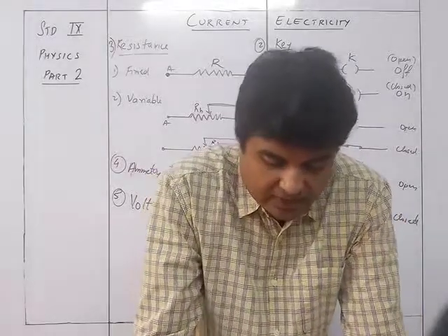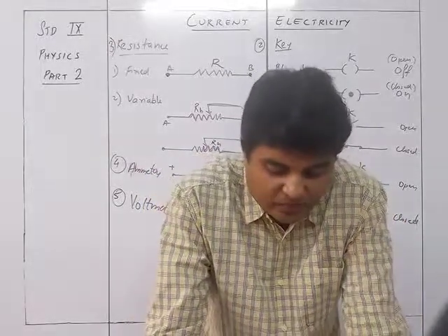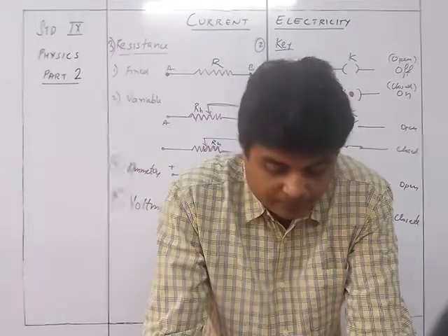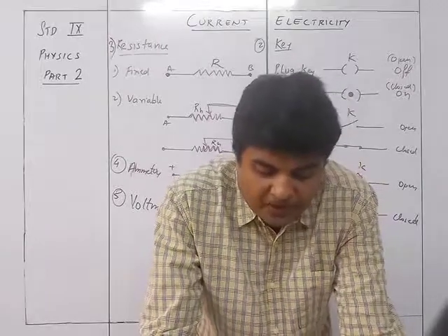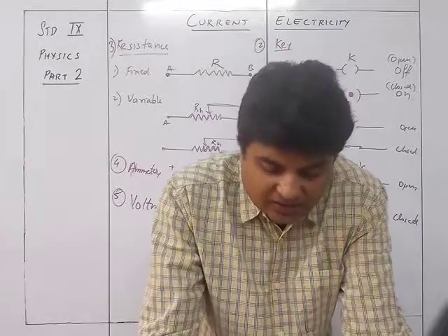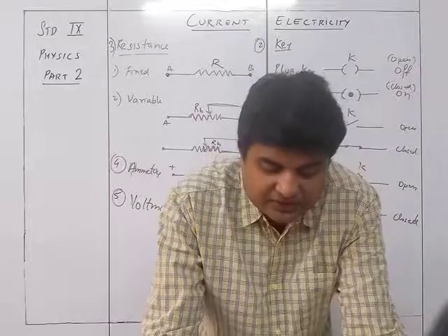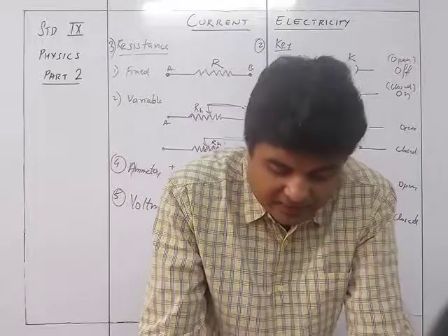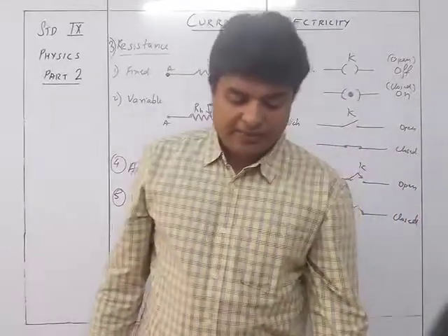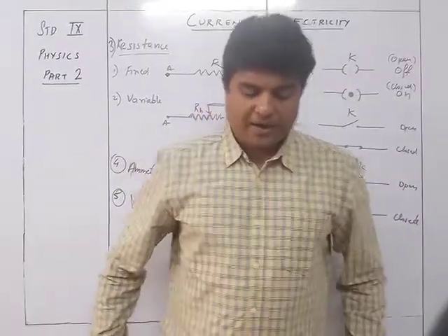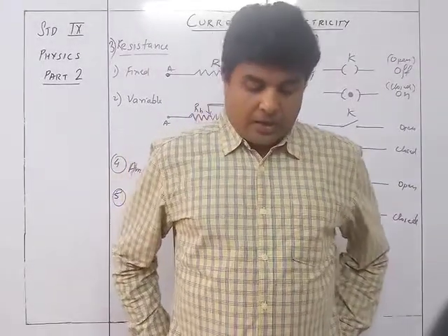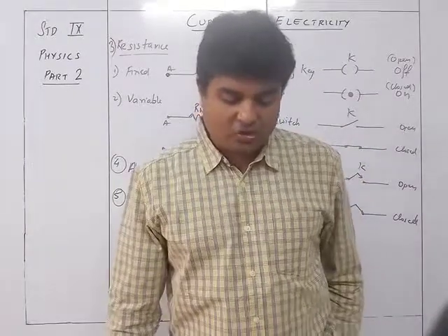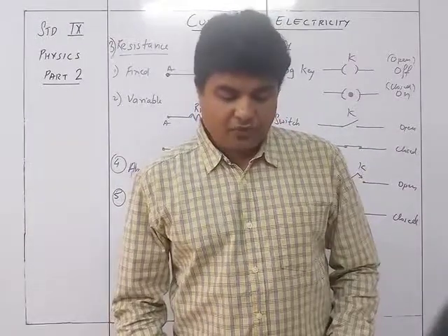The voltmeter shown in figure 9.2H is used to measure the potential difference between two points of a circuit. It is connected across the two points between which the potential is to be measured, that is, in a parallel flow of current. It is symbolically represented by the letter V enclosed in a circle as shown in figure 9.8. The positive sign marked at one terminal of it indicates that current must enter it through this terminal. Therefore, this terminal is connected to the point at higher potential. A voltmeter usually has a very high resistance so that it does not draw an appreciable current from the circuit.